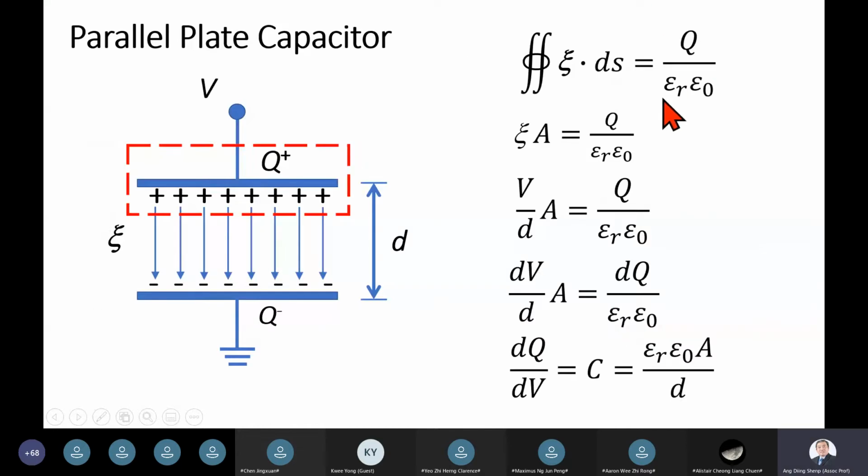So how does this polarization of the dielectric apply in our case? That is the reason why we need to include the relative permittivity here. Imagine the region that separates the two plates is not vacuum, but is made out of some material that is polarizable. During the application of the external electric field, there will be alignment of the dipoles, and the dipoles themselves will create an electric field that opposes the applied field. As a result of the polarization of the medium, the net electric field across the two plates will be smaller.